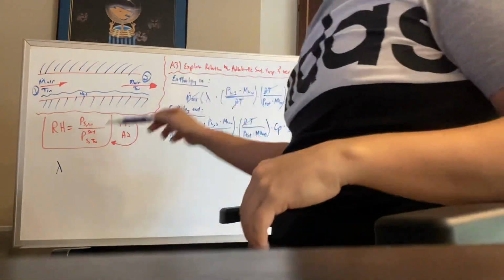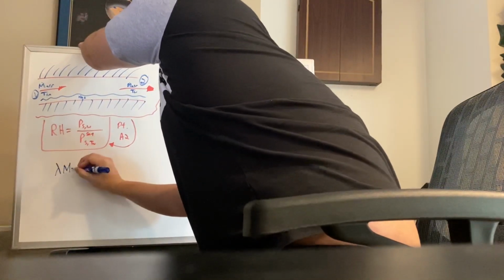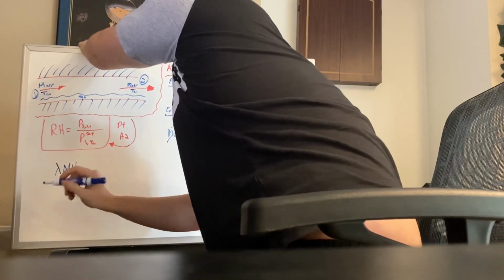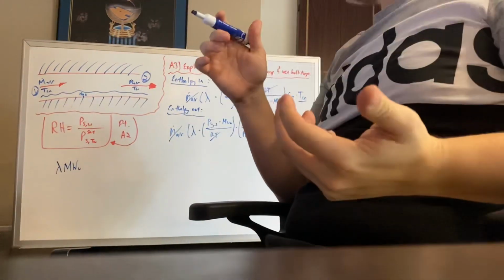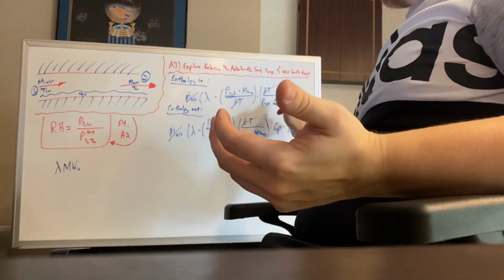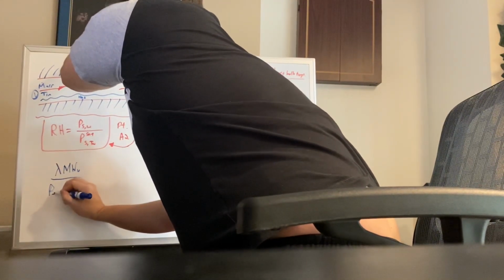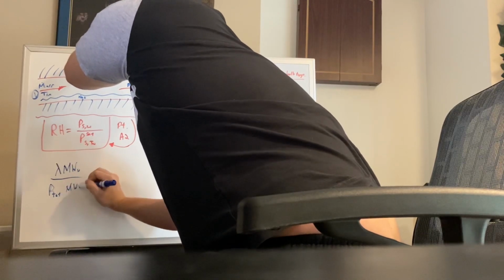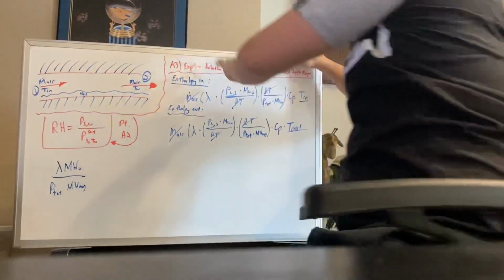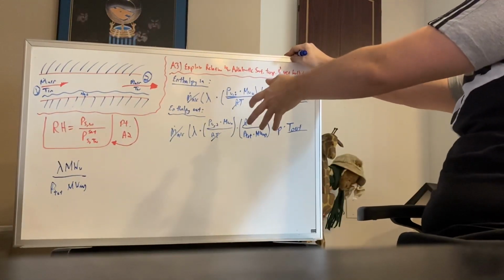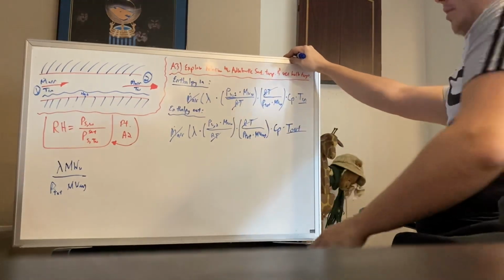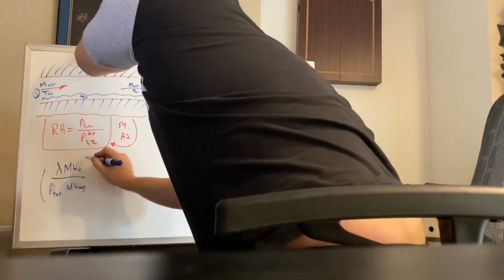Okay. So here on the left side, we'll have the heat of vaporization multiplied by the molecular weight of water, all over the total pressure multiplied by the average molecular weight. Write that. This is because we're condensing this part of the equation just to make it a lot easier to manipulate to get what we're trying to find at the end. This is going to be the first coefficient on this left side.